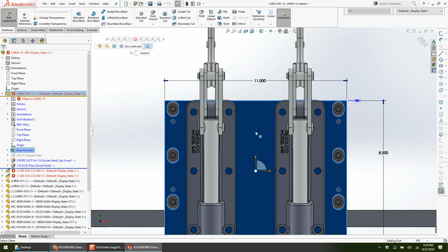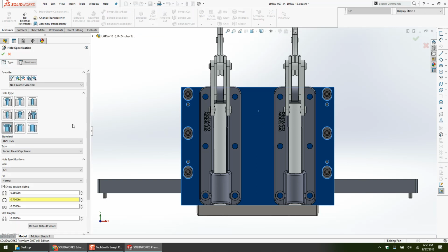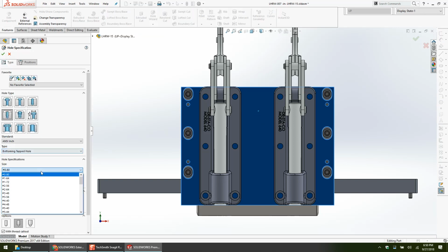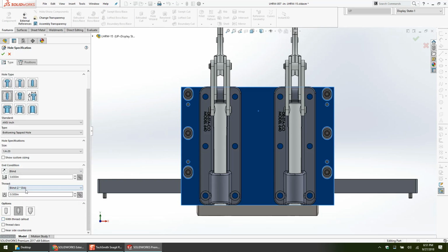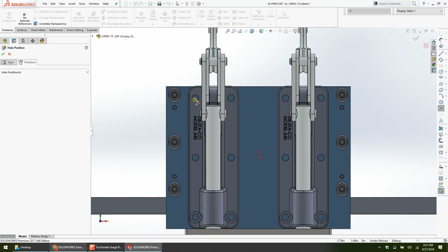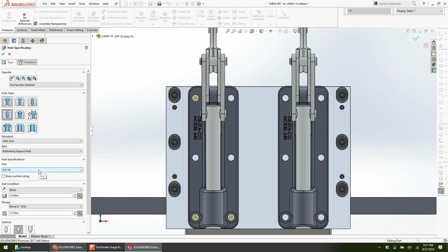Okay, so I'm editing the part inside the assembly at the lowest possible level, and I need a bolt hole pattern for these 2 Destaco clamps. So I'm going to launch my hole wizard. I don't know what size this is, so we're just going to say it's 1/4-20, because that sounds exciting. It's like my favorite hole ever. And I'm going to click here, going to click there, going to click there. That hole looks really small. Let's bump that up.